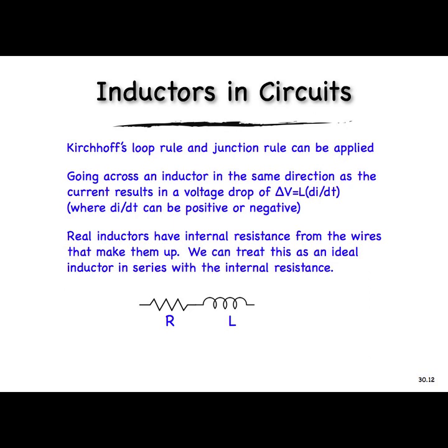And I will also take the total energy stored and divide it by the volume of space in which the magnetic field is confined. That will give me the total amount of energy per unit volume. Dividing this by the volume of this core, if the cross-sectional area is A and its length is 2 pi r, I can divide this by A times 2 pi r. That gets rid of the A, and dividing by 2 pi r makes that 2 pi r squared. And I'll call that the energy density.